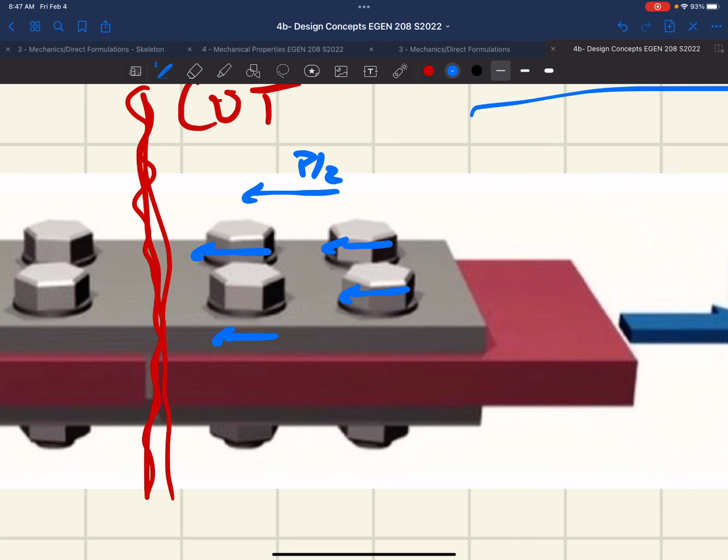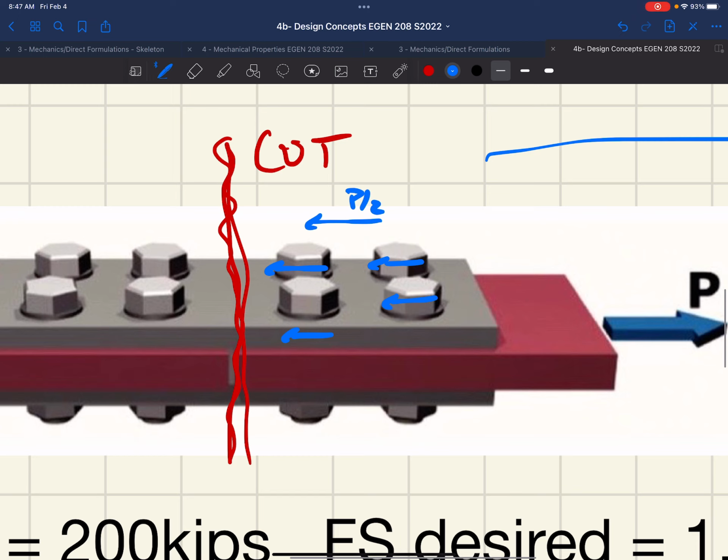Yeah, so if you said single shear, it would just be like 2 plates instead of 3. Yes, correct. Yep, if it was single shear, you would then essentially delete this bottom plate, and that force, P, would be going through just one shear plane in each of these bolts. The bolt's only trying to shear off at one location. So you just have straight up P. Yep, so instead of P over 2, this would just be P, right? And you would divide P by 4 instead of by 8.